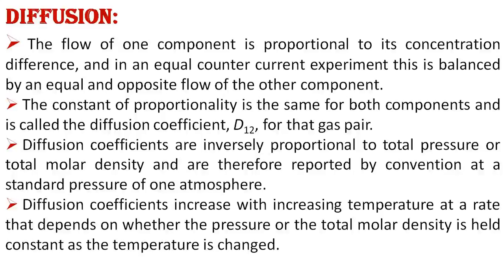The constant of proportionality is the same for both components and is called the diffusion coefficient for the gas. The diffusion coefficients are inversely proportional to total pressure or total molar density of the gas and are therefore reported by convention at a standard pressure of 1 atmosphere.